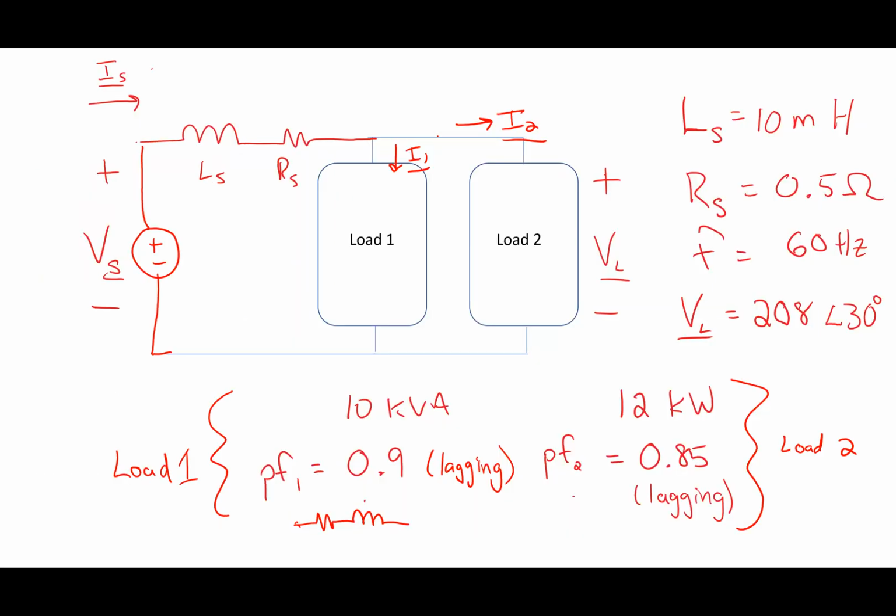Sometimes I like to say power factor 0.9 inductive, but it's more common to call it a lagging power factor or a leading power factor. That's more normal, because you don't come across a lot of capacitive loads. You come across more loads that are inductive. And why would that be? I can make up a problem that has whatever, but in the real world, why is there more lagging load than leading load? Why more inductive load than capacitive? Any ideas?